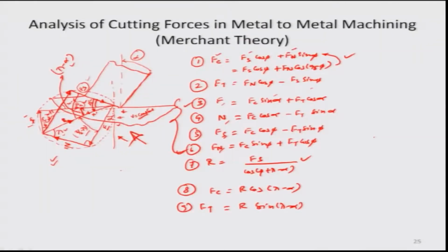Let us look back and see what we mean by that. So, there is a shear plane formulated in this particular direction, and we have an uncut chip thickness which is roughly this thickness right here. So, this is T1, how far it is from the zone of machining on the vertical axis. So, obviously, the total area that this particular plane would have multiplied by the ultimate yield shear stress would define the amount of shear force that is necessary to separate the chip from the workpiece material.